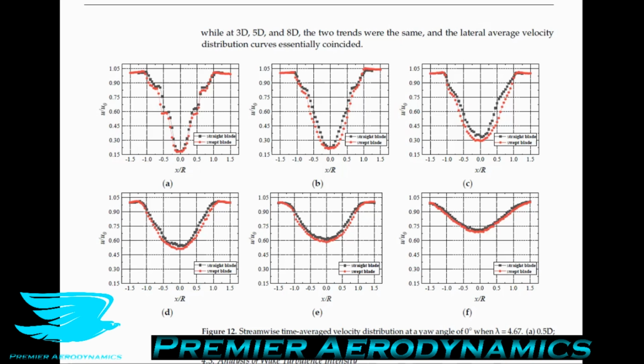So in other words, these tip vortices, and vortices in general, are manipulating the flow downstream, and instead of getting the regular V shape, you actually get a slight increase near the center of the rotor, and then deficits behind it. So it's not a lot, but it is slightly more than what you'd expect. So it's not the typical V shape. That's what they mean here.